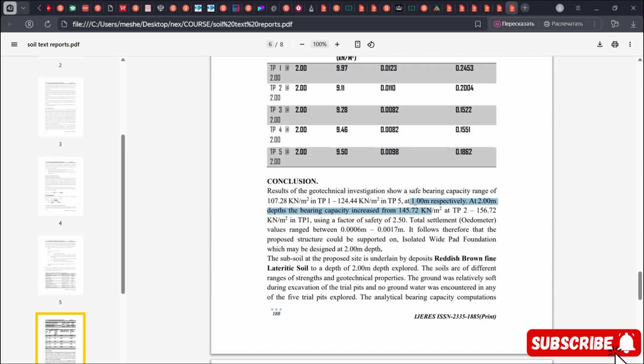At 1 meter depth, they have to do what? TP1, TP2, TP3, TP4, TP5, TP6. So what they are saying here is that at 1000 millimeter depth, the safe bearing capacity is from 107 to 124 kilonewton per meter square. Okay, kilonewton per meter square. For me, from experience, it is important to take 150 and above.